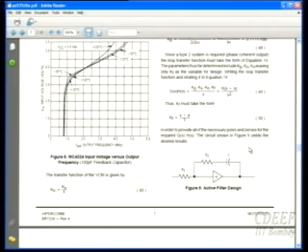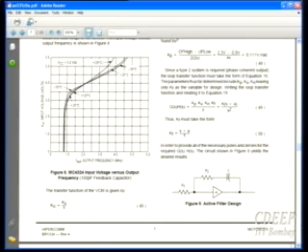This active filter actually does the same work that the charge pump does, and by adding this RC as a feed-forward path, actually they are generating a zero. So the transfer function of this will be similar to the transfer function of a simple first order loop filter that we have, RC at the output of the charge pump. Okay, so it's similar to that.